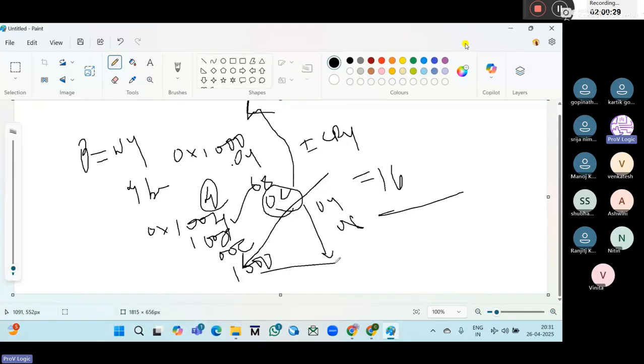Okay, so whenever you need to load a fixed block of data, you need to start at some address but must stay inside the boundary. So increment would continue outside the boundary, but wrap doesn't. Within the boundary it should stay. Okay, that is the difference. Increment means sequential; wrap is also sequential, but it rounds back to the initial boundary value.